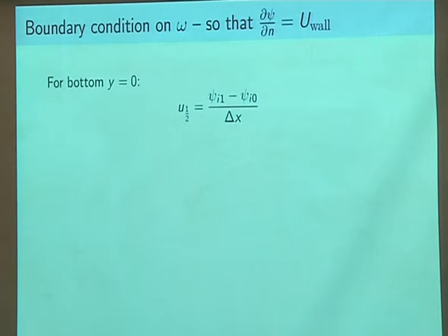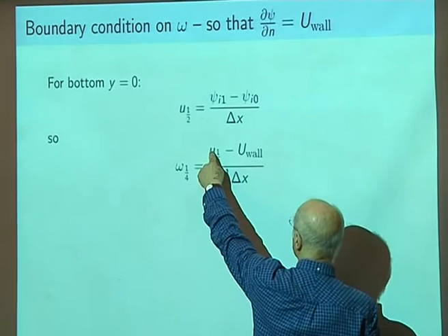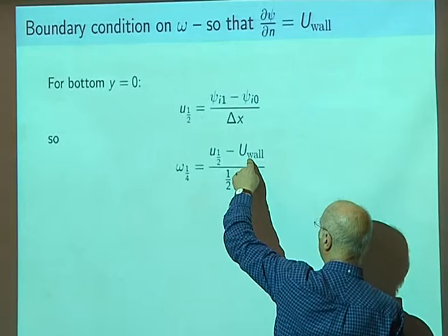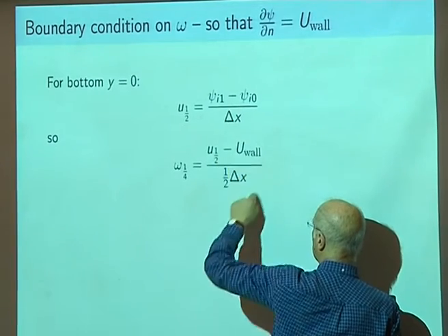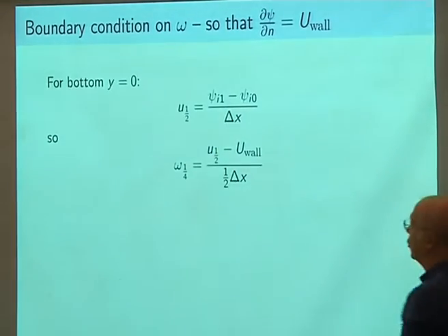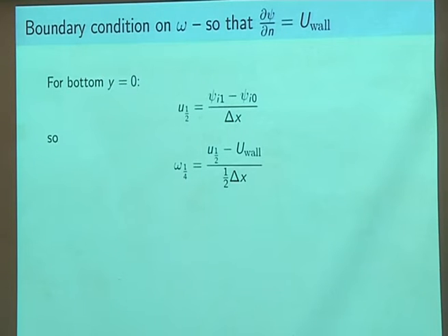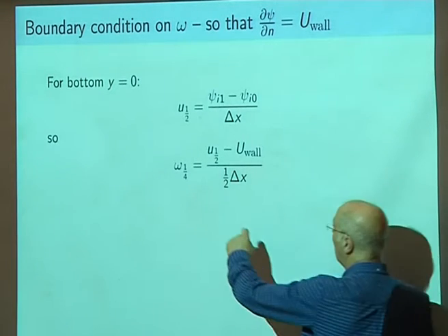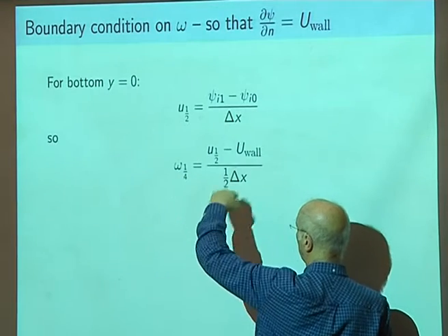So I've got the velocity at a half point in, and then if I take the velocity half a point in and away from the wall, I can take the y derivative of how the horizontal velocity u is varying to get du by dy, which is the vorticity when there's not a vertical velocity on the wall.